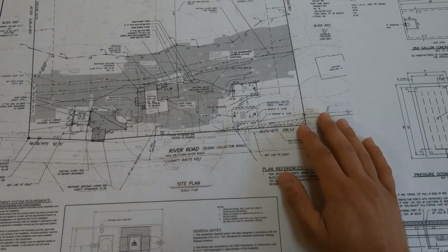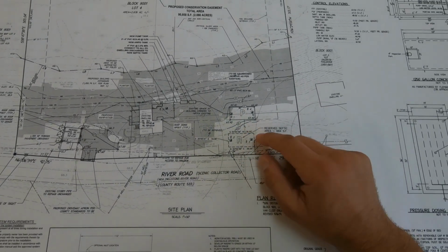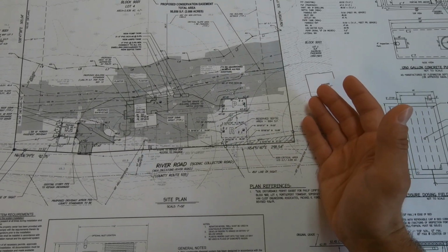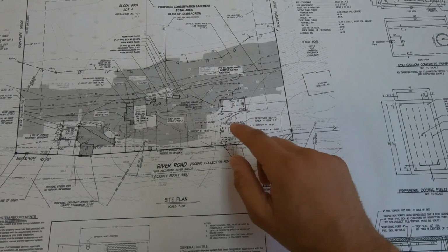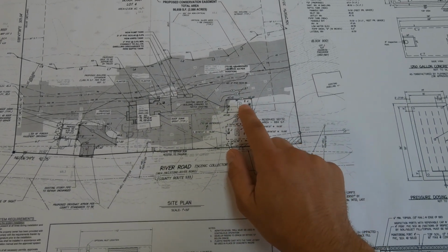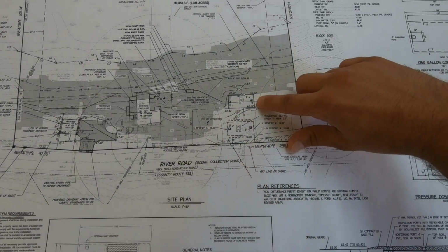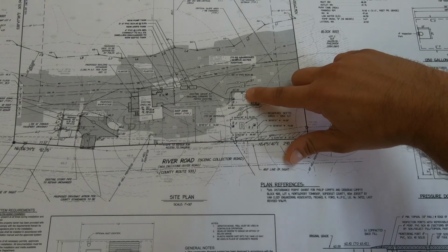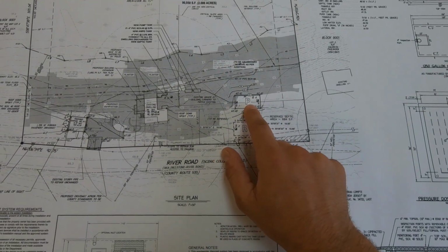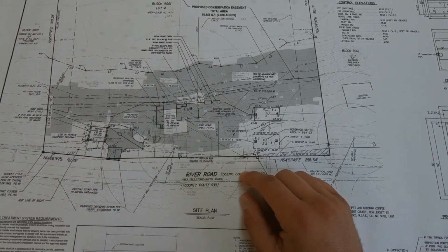field. On this particular set of plans, we also have a reserve area, a reserve field. Depending on the town that you're working in, they may require that you have something like that. In this case, I don't know if it's required or not, but there's a reserve field. This is the field that we're interested in now. This is the proposed septic field. And again, you'll notice here there are small dimensions. It's 19 feet by 36 feet. So that's the size of the field. That's basically the system. Those are the components we're concerned about.